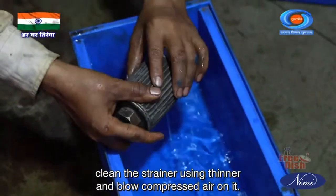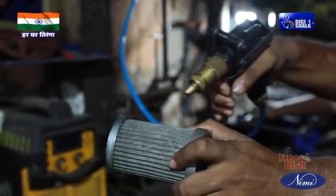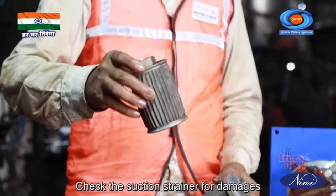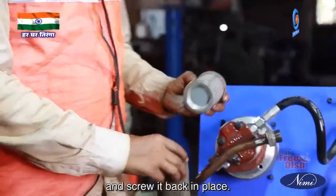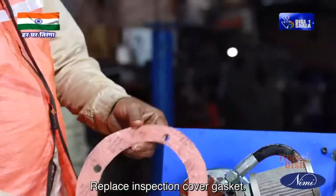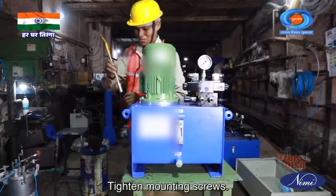Clean the strainer using thinner and blow compressed air on it. Clean the reservoir thoroughly. Check the suction strainer for damage and screw it back in place. Replace the inspection cover gasket. Tighten the mounting screws.